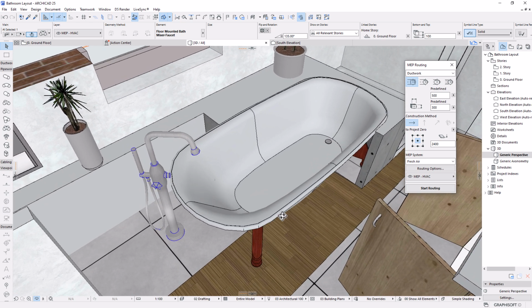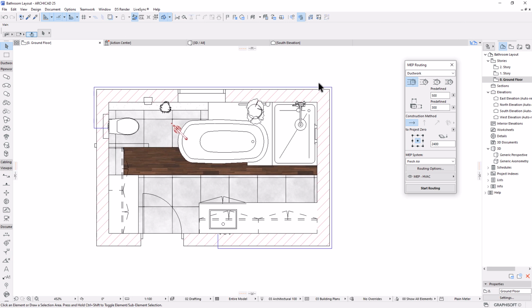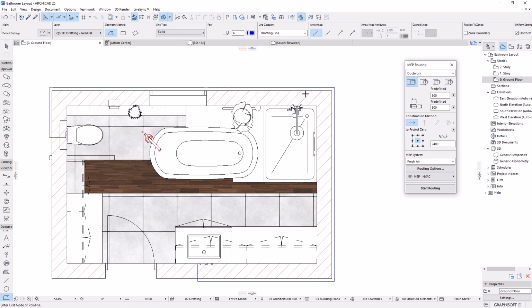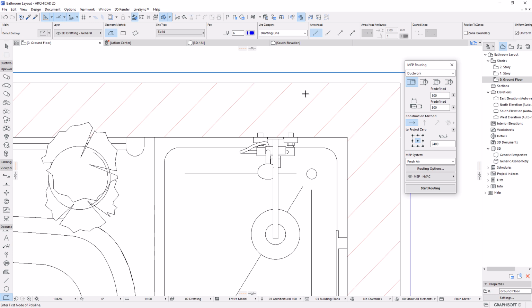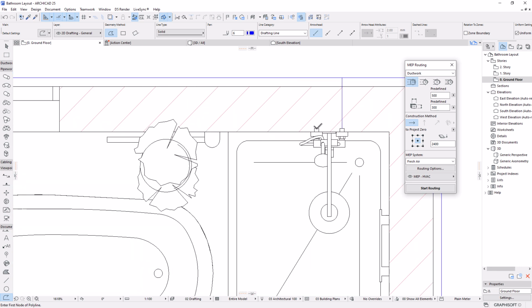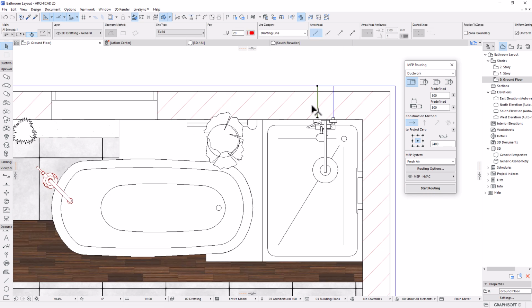Perfect. All right, so now let's go back to our draft and complete that. I'm going to pick the parameter by holding Alt on your keyboard and then click on this line. I have another cold water supply to the shower tab. I'll just draft it that way. Here it's hot water. I'm just going to select this and then change it to color red.